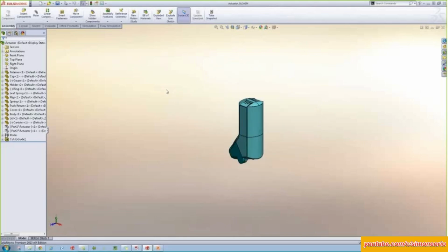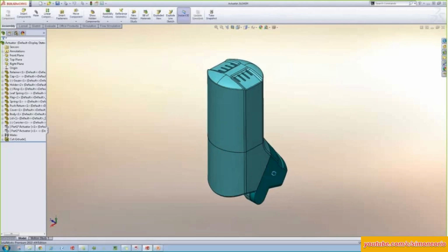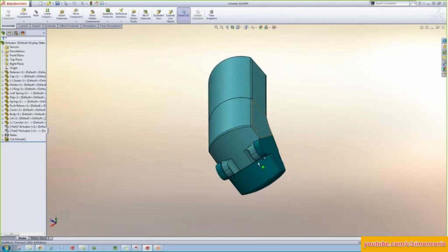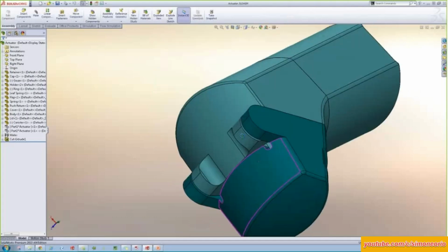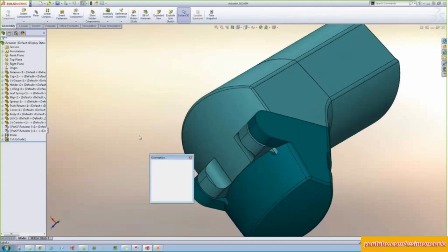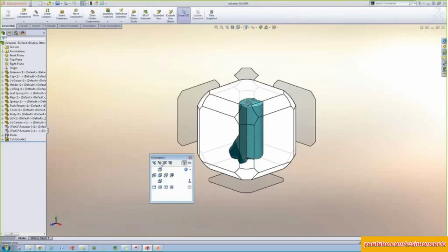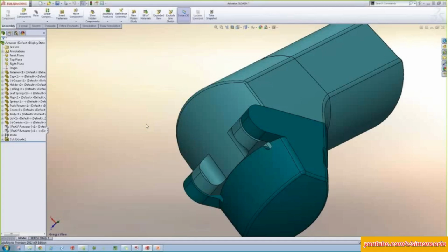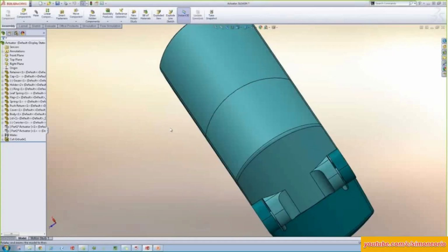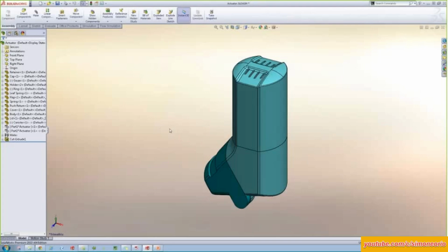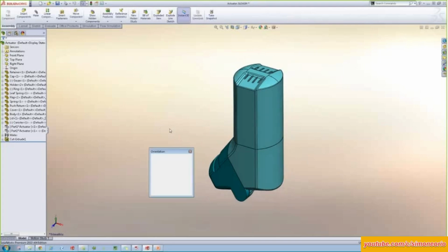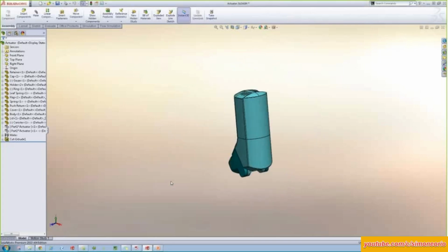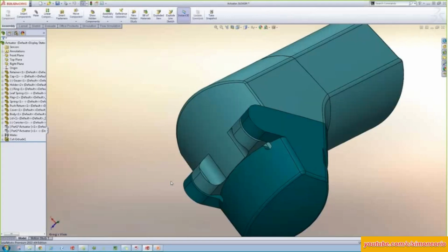You can create your own views as well. So if I know that the hinge on the bottom of this model is going to be really important, and maybe I want to use this in a drawing later on, I can just hit that space bar, hit New View, and add a view name to that. I'll just call it Greg's View here. Now, anytime I'm moving around in standard views and I want to get back to that previously set up view, I just hit that space bar and click on that view that I've saved. So, some really easy ways to manipulate and move around your model.